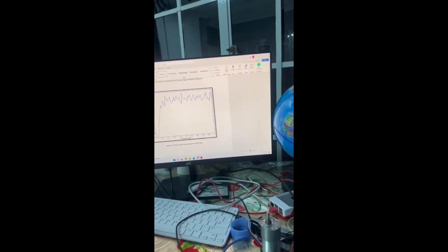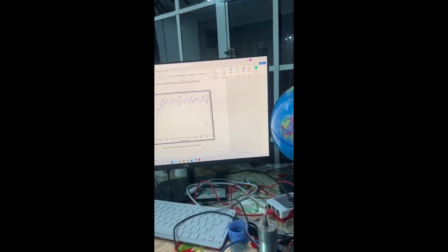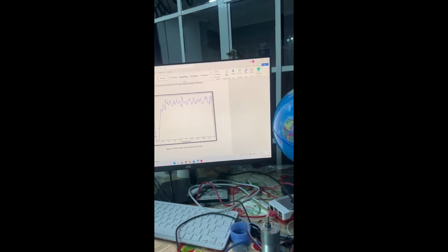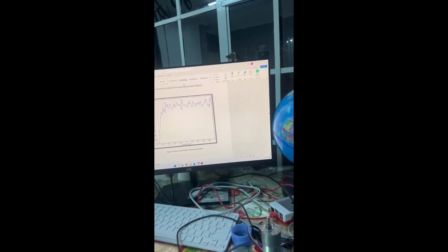The steep rise continues up to 1.4 seconds, indicating a strong initial torque, and then gradually slows down towards steady state. The motor reaches around 63% of its final value relatively quickly, confirming it's a typical first order system.